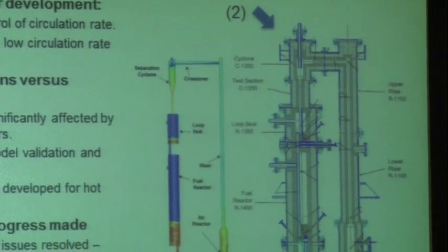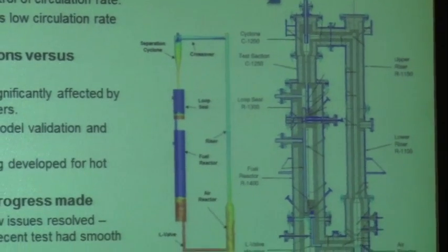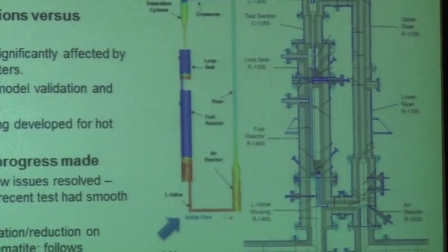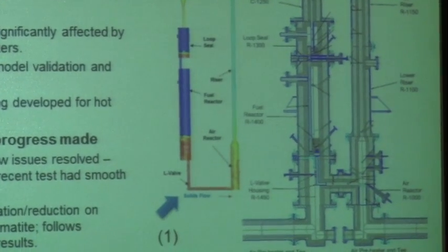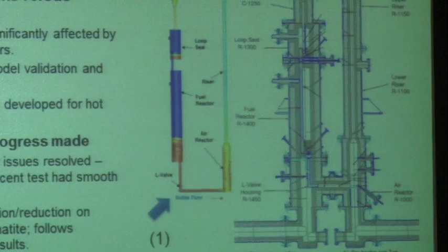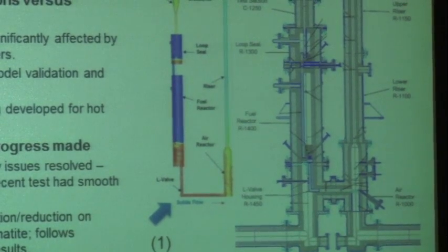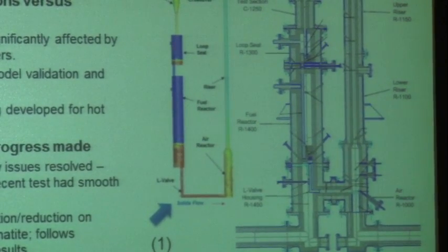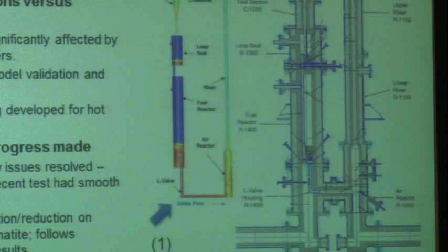99.99 means in a number of hours you've lost a significant mass of small material, which in a real process you would recycle and put back in because you'd catch it in the bag house. In a lab environment, it means your experiment's done, right? Because you just lost all the material out of the top. I mean, we've run these tests for multiple days. So separation efficiency starts to become a practical issue that drives the design, right? And we actually found a great way to address that, which I won't get into today.